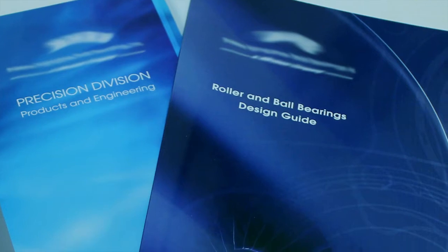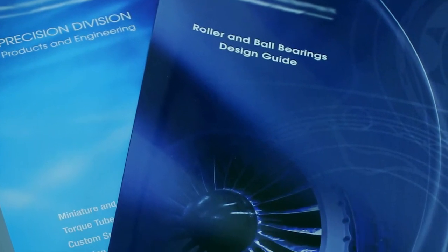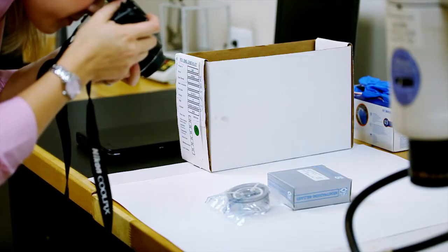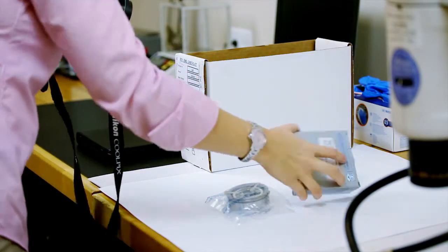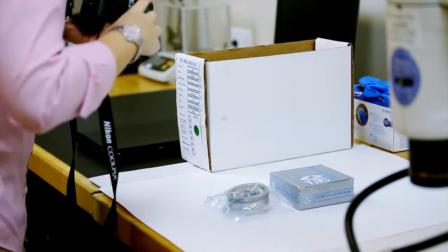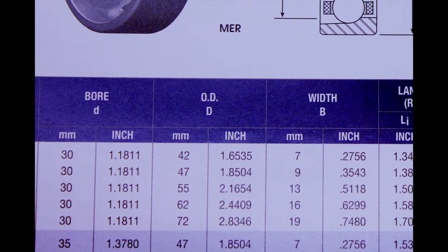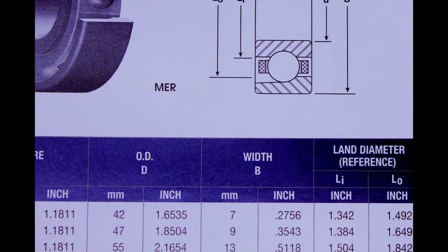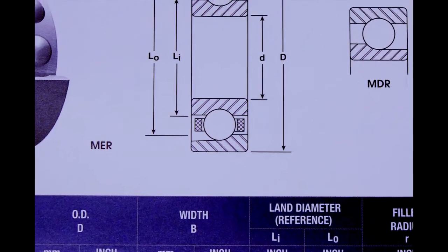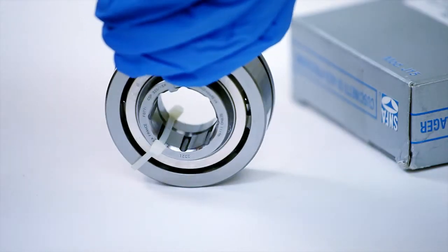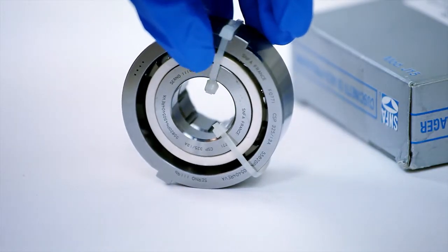Manufacturing catalog data is researched to help the engineer understand who made the OEM parts. If the manufacturer has indicated any internal part number, the engineer can research this to typically find general dimensions specified by the manufacturer, such as bore diameters, outer diameters, widths, and materials. As detailed photos are taken of the parts and packaging, the engineer is determining which features will fall into the assembled measurement condition or the disassembled measurement condition.